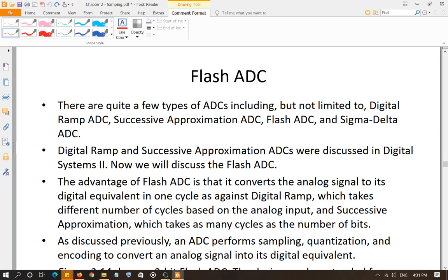There are certain stages through which a signal goes through before a digital code is generated, and those steps are: first, the analog signal is sampled, that is, different points of the analog signals are collected at specific time instances, which are called sampling time. Once you have samples of the signal, then each sample is converted into a quantized value. It's an analog value, it's called quantized value, and the job is done by what we call a quantizer, which is part of an ADC.